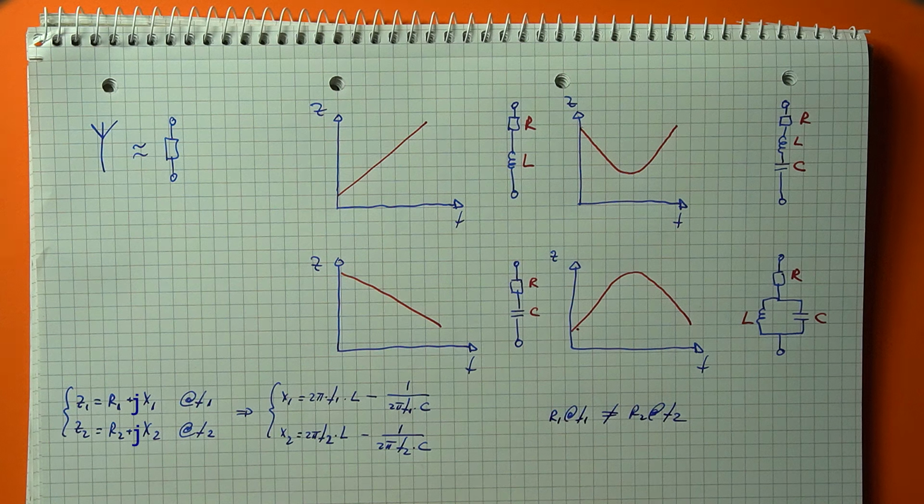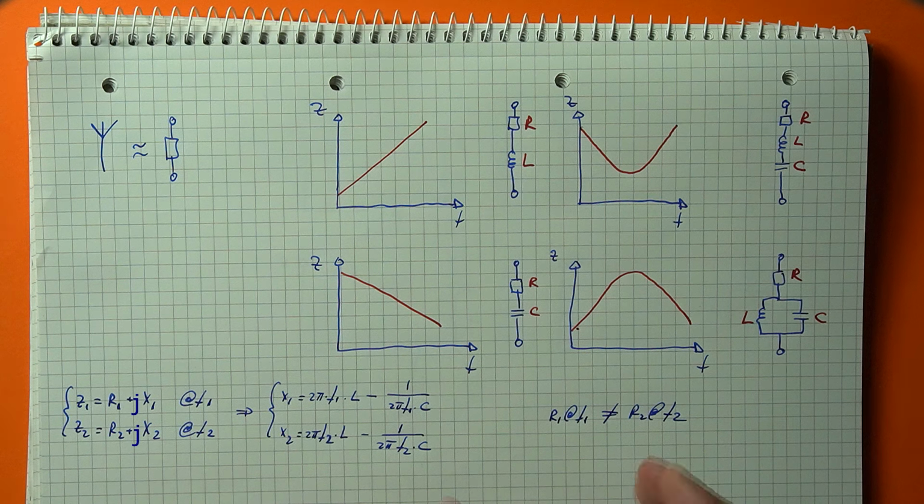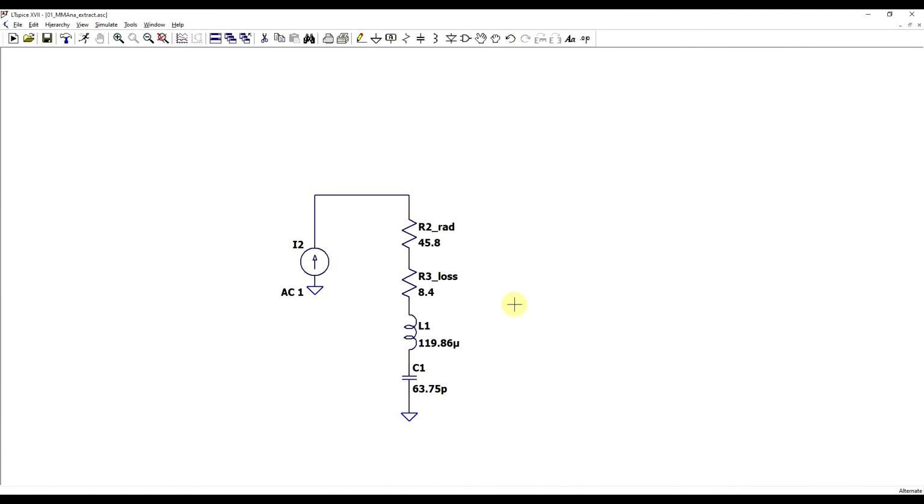So here you can just take one of the resistance values, either one of the extremes or an average, and just live with that. And then, based on the ideal and real material simulations, this resistance value can further be split up to account for loss and radiation. So after doing a bit of calculation, we can create our RLC model.